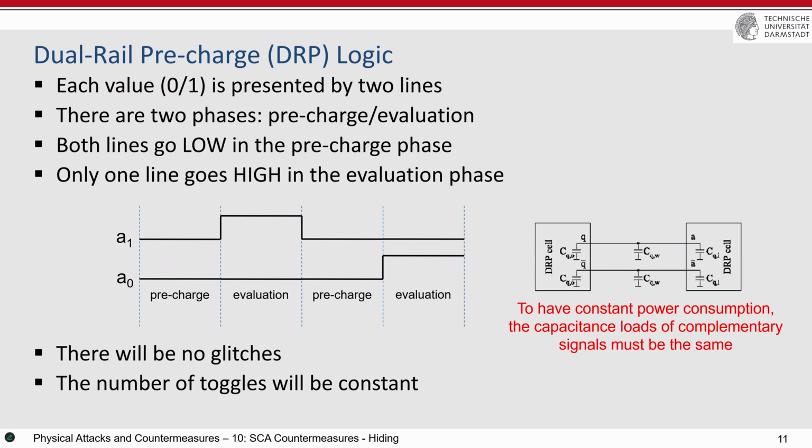Although you say, oh, super small, but if you measure enough traces, you will see this will be propagated. It's not only one signal. This is the entire AES, or the entire S box. And then for different inputs, there are 200, 300 different capacitances that are charged. And if you have another input, some other capacitances will be charged. And then if you sum them up together, you will see a very big difference between the amount of power consumption which is required. Then you should try, and there is also some research on that, to route these signals as similar as possible inside your circuit.